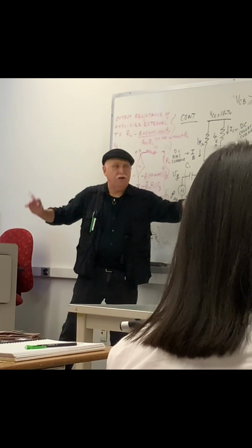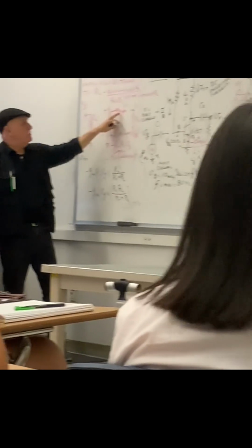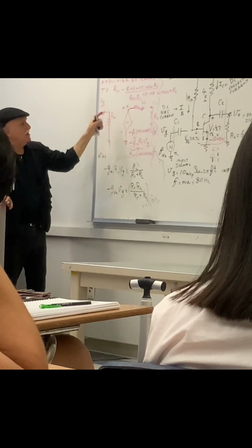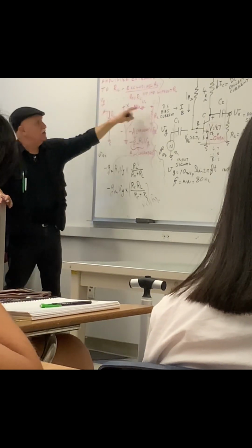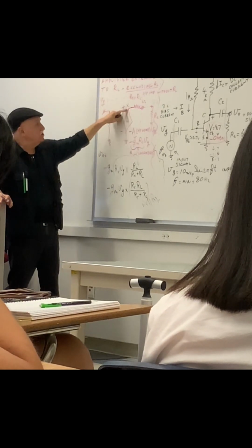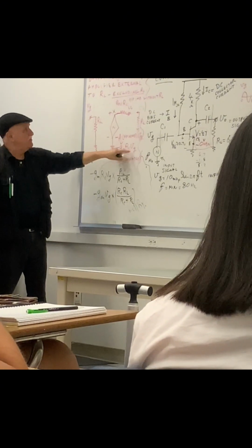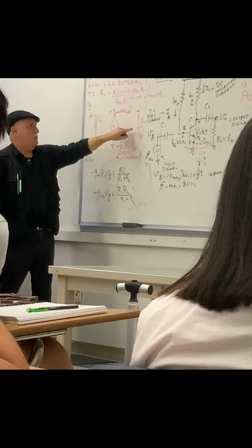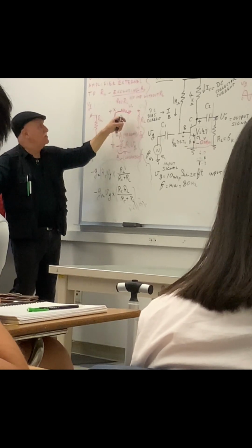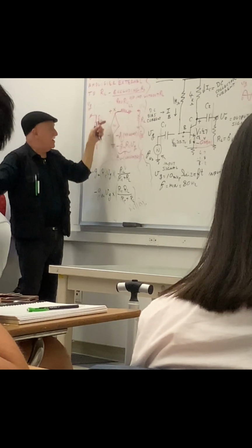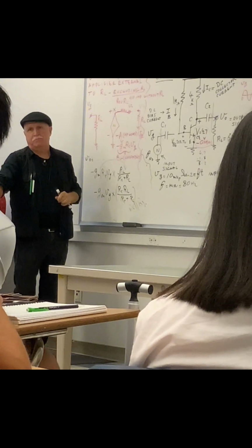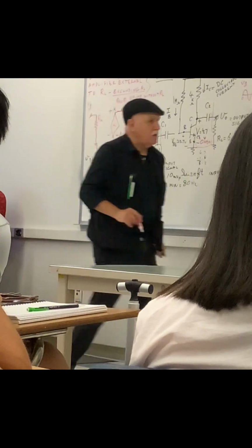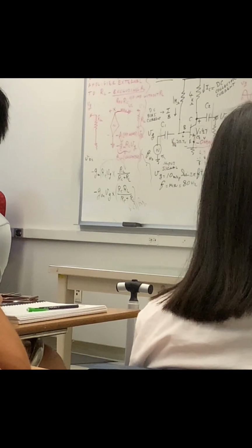You have a load there, fine. You put the load over there, jumper the two together, and then calculate the voltage transfer from here all the way to here. So VG transfers here to GMRC VG, then GMRC VG voltage transfers here by an additional voltage divider, RL over RO plus RL times that voltage. You've got to get this, see? So this is done.